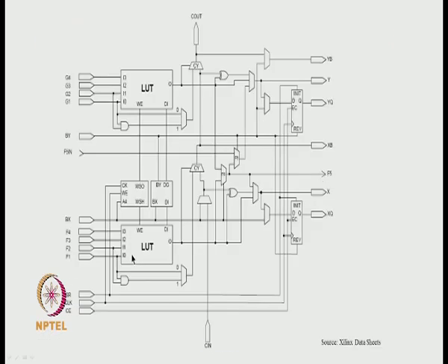Okay. So let us go to the CLB, the slice diagram, and you can see that here is where AI and BI are connected. You form the AI exclusive-OR BI in this lookup table, and that is coming here to this exclusive OR gate, and the carry in from the previous stage is coming here through this mux and is combined with the AI exclusive-OR BI, and you get the sum.